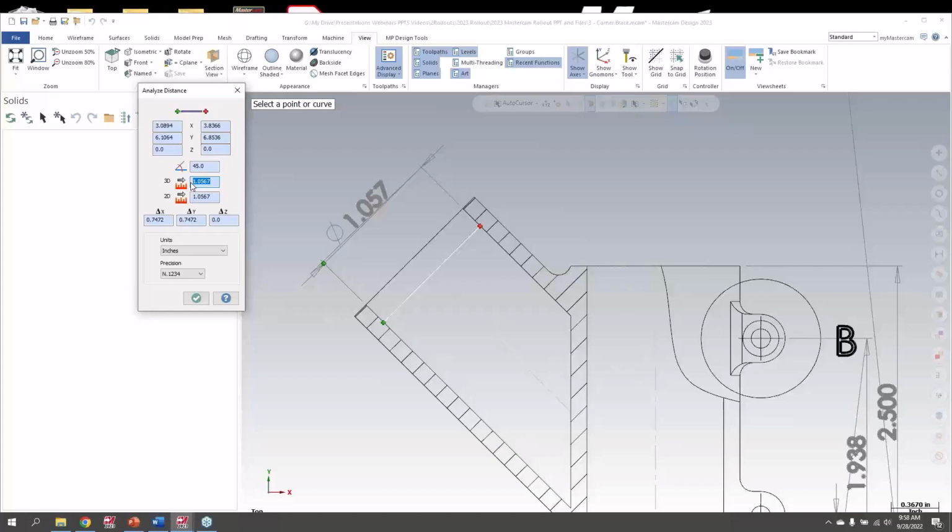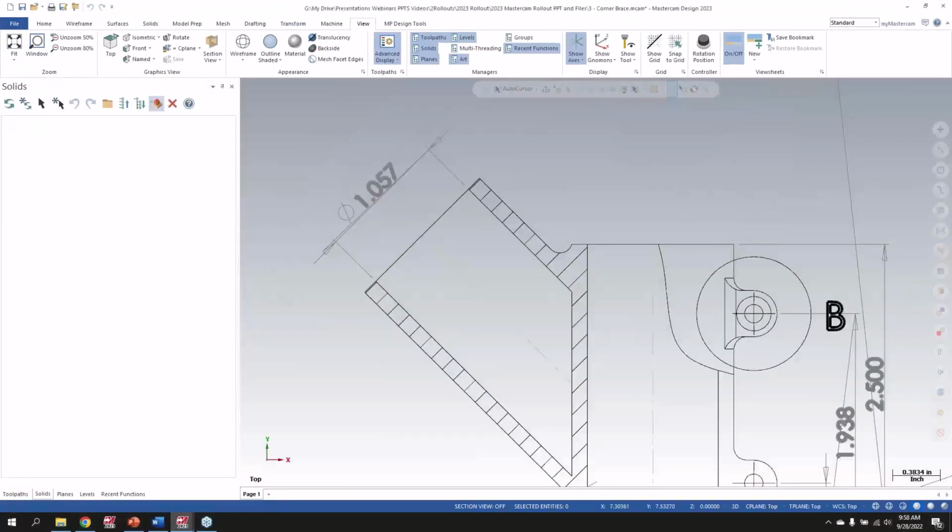So if I brought this in and say my measured value in Mastercam was exactly double what the dimension is on the print that I dragged in, then I would maybe want to adjust the scaling in the transform tab and scale that PDF to the correct size. But just a little additional file support there for 2023 here.